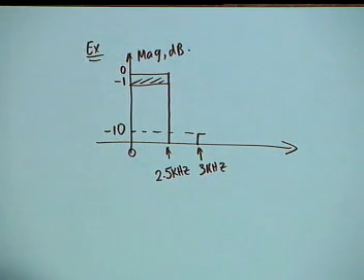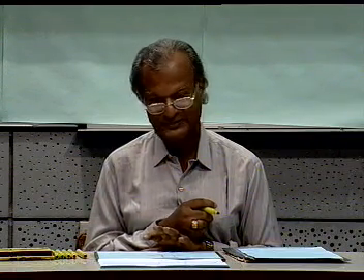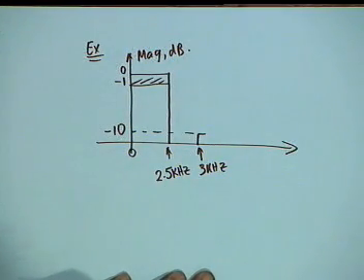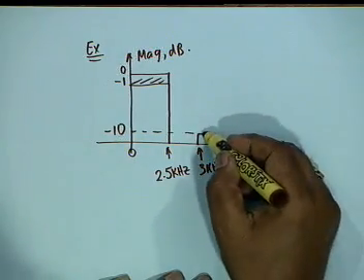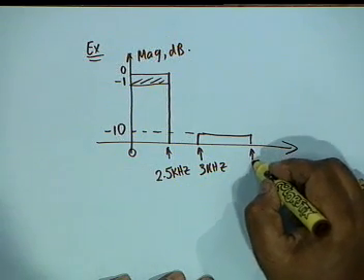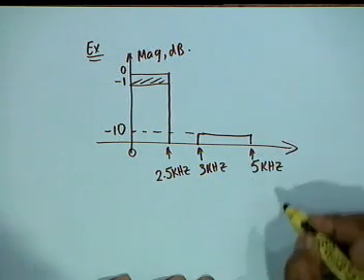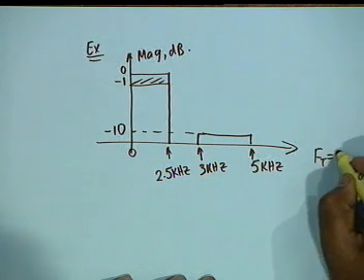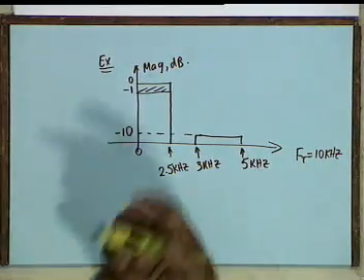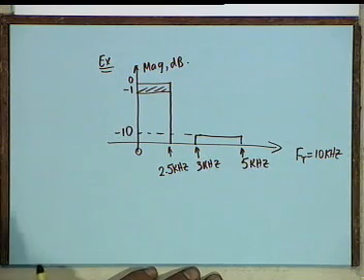One could expect that this would be satisfied by a sufficiently low order filter, because it's only 10 dB, but you must also see the transition is pretty narrow. And they said we don't care what happens beyond 5 kilohertz, which means that 5 kilohertz is the end of the base band. So the sampling frequency f_T must be 10 kilohertz. Either this is given or the sampling frequency is given. Without that you cannot work.